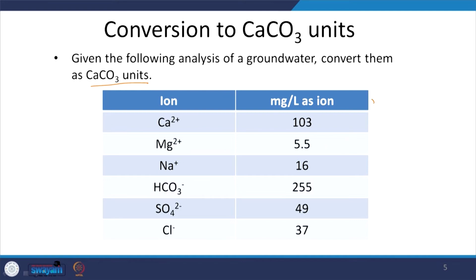If we have milligram per liter of a particular compound, Ca2+, first I am going to divide it by the molecular weight, grams per mole of Ca2+, right. Then I will get it in moles, and then I know that it is 2 equivalents per 1 mole of Ca2+. Why is that? Because of the charge. Here it is 2+. So now I have it in terms of equivalents.